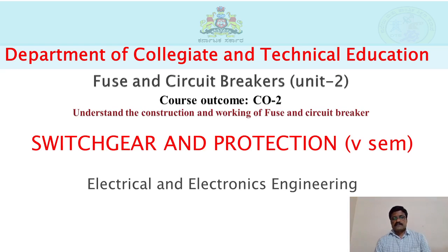We have already discussed that transformer oil has high dielectric strength, high thermal conductivity, and very good insulating property. So the maintenance of the oil circuit breaker requires checking the contacts as well as the oil.